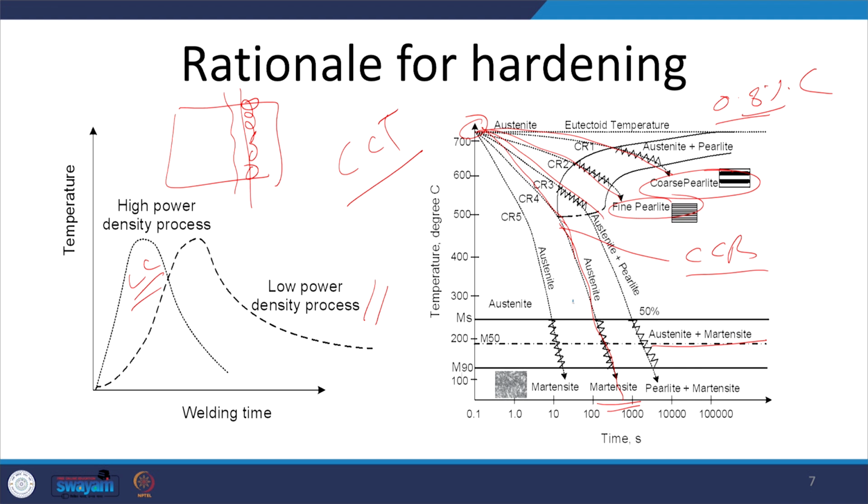If the phases are pearlitic, fine pearlitic or part martensitic, then the hardness will be a little lower as compared to the case when 100% martensitic transformation takes place near the cut edge. That will lead to significant embrittlement of the cut edge, which will affect the deformation and forming of the steels.